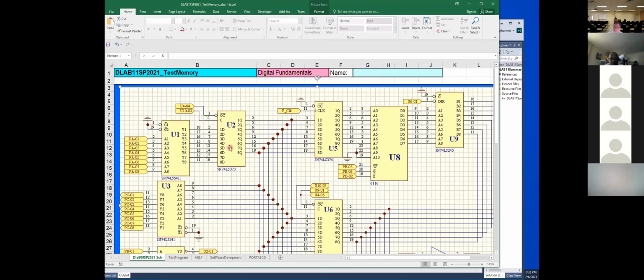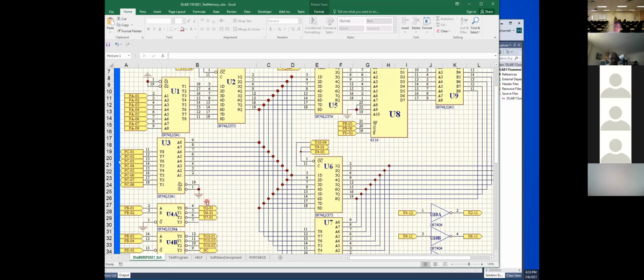So when you write port B, if you were to write 0x03, that would just enable the latch and not the output. Is that correct? Output pin 1 must be 0. But if I don't want the output, I only want to latch it, then that has to be 1. Latch is here.